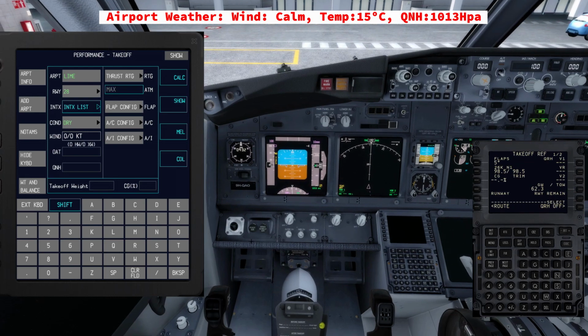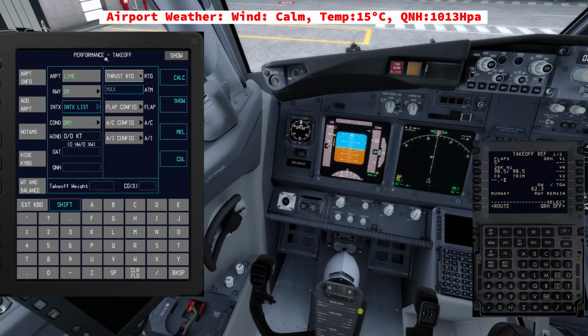But again, depending on the operator, I know some operators have different limitations, but that's to give you an idea. The crosswind component is very important, because depending on the crosswind, the operators, and the procedure that you're using, you may have to apply further correction, and sometimes depending on the crosswind it is a captain only takeoff. So that's why as well it's very important.